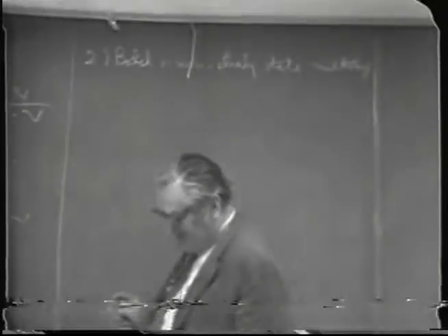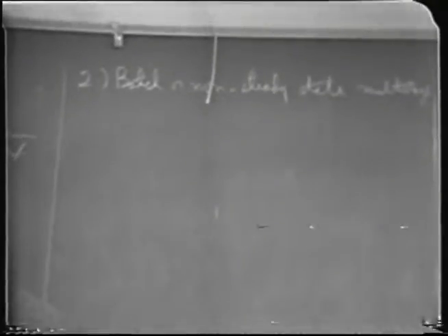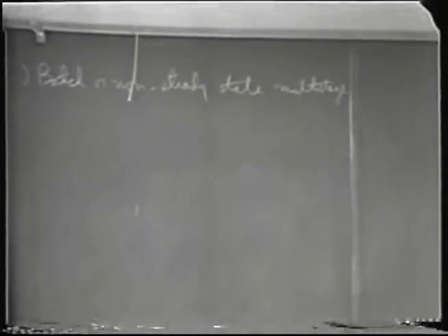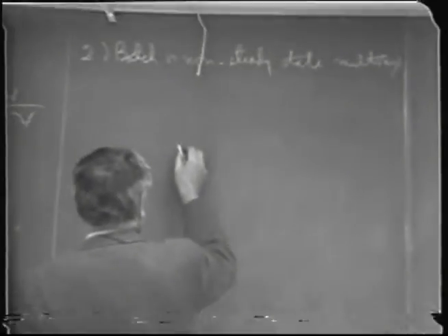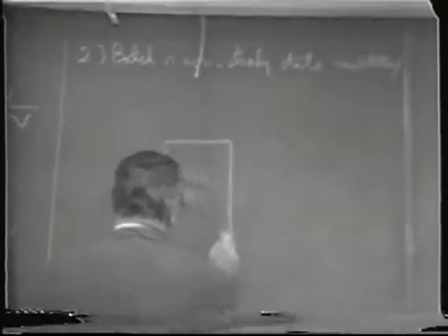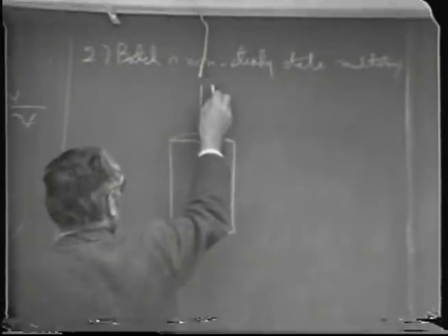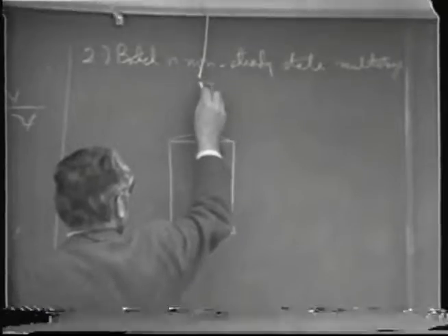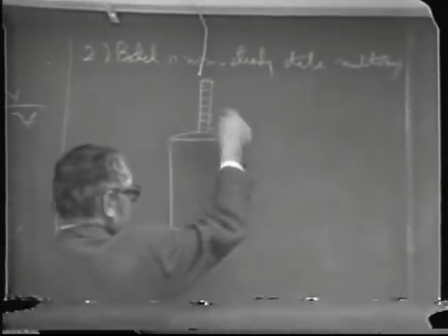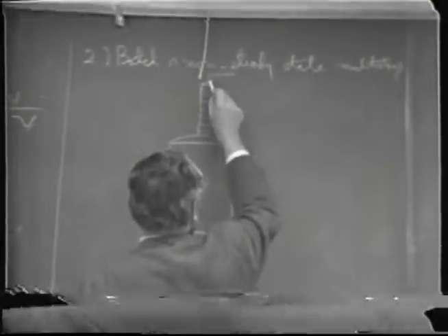Well, this is accomplished by combining a simple pot or a boiler with a fractionating device, or in other words, a plate column. And so in essence, the equipment that you use to conduct this would be some sort of a pot or boiler, which you introduce the liquid. And then we put a plate column on top here, either on top or maybe set off the side where the vapor is carried over to it. And the vapor from that, of course, goes off to a condenser.